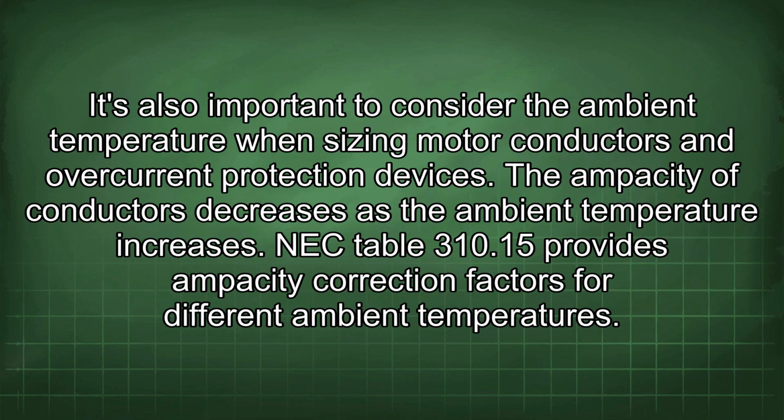It's also important to consider the ambient temperature when sizing motor conductors and overcurrent protection devices. The ampacity of conductors decreases as the ambient temperature increases. NEC Table 310.15 provides ampacity correction factors for different ambient temperatures.